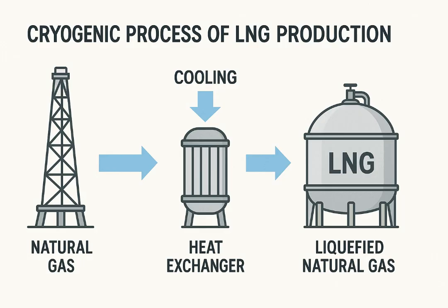7.0 Application of the concept of real gases. 7.1 Production of liquefied natural gas, LNG. The liquefied natural gas, LNG, is made of methane with the highest composition of about 80% with few amounts of ethane as well as minute concentrations of propane and butane. The LNG process is a practical example of how the concept of real gases is applied in real-world industrial processes.